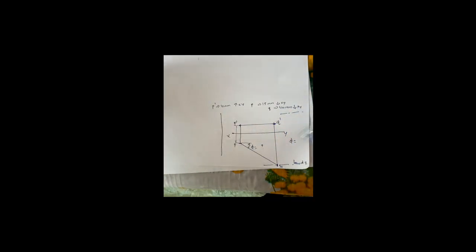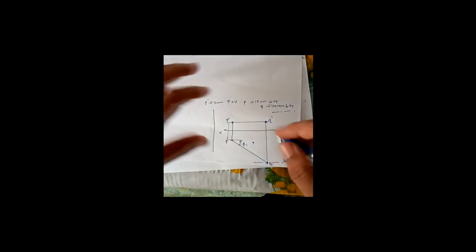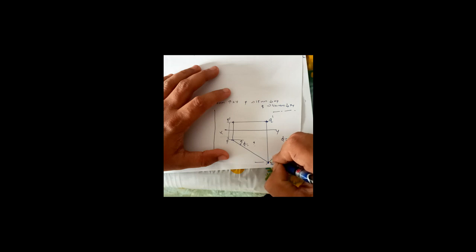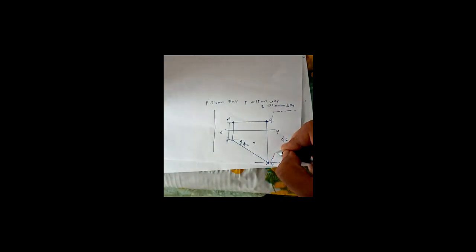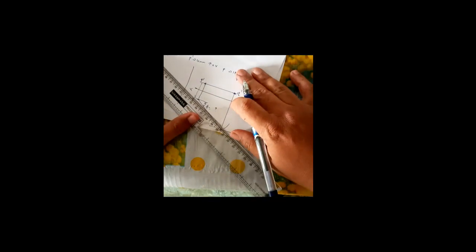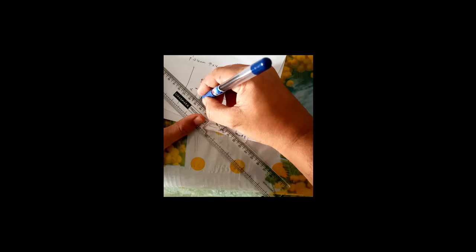And one more thing, you have found PQ by drawing an arc. So for dimensioning it, extend that arc. This should also be a light line, I am telling once more, it's a light line. Draw a light line from here to here with an arrowhead, and I am marking it as R50.